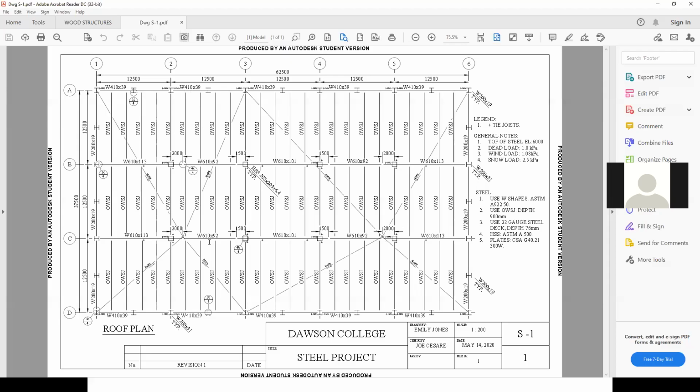And then once he decides, because he's got a limit on how big of a basin he's allowed to have on his roof, so there are architectural constraints, and he'll tell you what those are. Then you have to figure out how to adjust your steel so that you can create that slope for him so that his roof drains properly. And then from there, the mechanical engineer decides the size of the drain required. It's going to be a 4-inch roof drain, a 6-inch roof drain, and so on. So these are all things that get coordinated between you, the architect, and the mechanical engineer.